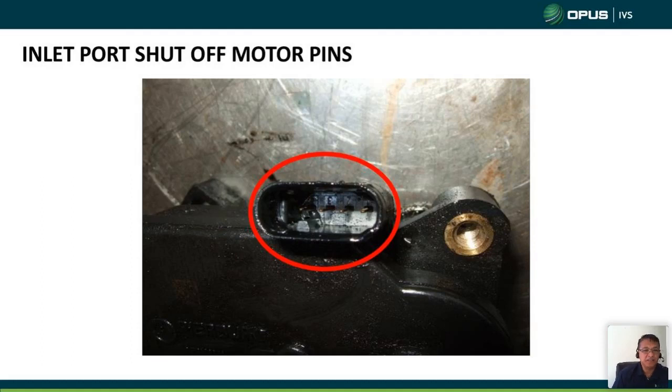So in some cases, they just put the fuse in, clear the fault, bang, the engine runs okay. But like I said, you haven't rectified it correctly because you didn't find the cause of why the fuse is blowing.